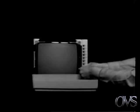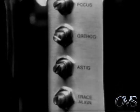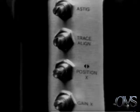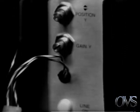By loosening two screws, removing the intensity knob, and disconnecting the quick disconnect plug for the power on indicator, the plastic mask can be removed. This exposes other controls used less frequently: orthogonality, trace align, gain X, and gain Y.